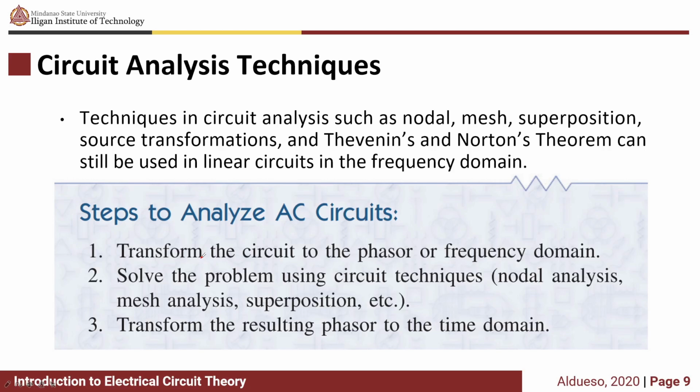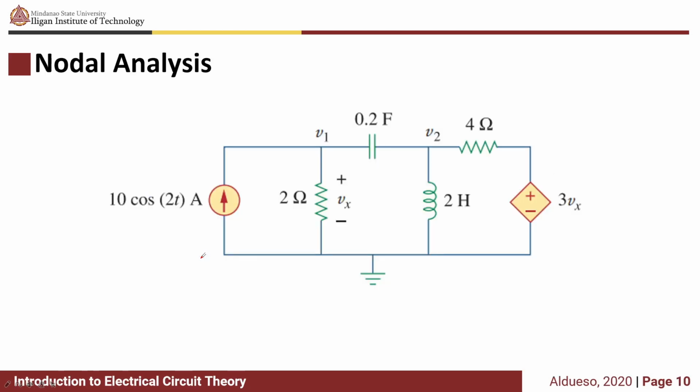So, steps to analyze AC circuits. First, transform the circuit to the phasor or frequency domain. Second, solve the problem using circuit techniques. Third, transform the resulting phasor to the time domain. So first, let's have this example and then apply nodal analysis.